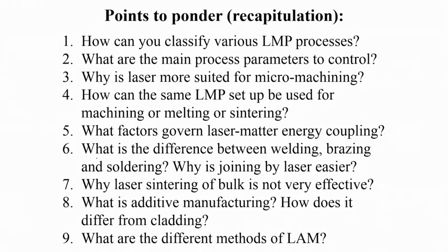Laser sintering is a bit problematic, particularly when you are dealing with dissimilar sizes or dissimilar composition, and that's purely because at a time you are heating only the surfaces of the powder particles and not their entire bulk. But one can actually use laser sintering in combination with application of pressure and then make a denser and stronger compact or sintered product.